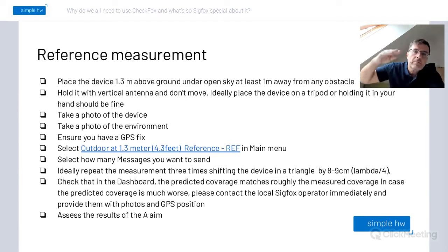So if you are measuring it under a hill, so the hill is covered very well, and if you are like 20 or 30 meters under the top of the hill, the coverage model predicts that there's still good coverage, or the API predicts that there's still good coverage, and it doesn't need to be because you are in the shadow of the mountain. So always think about, even when you are evaluating the results, that we are still working with averages, and assess the topography of the place.